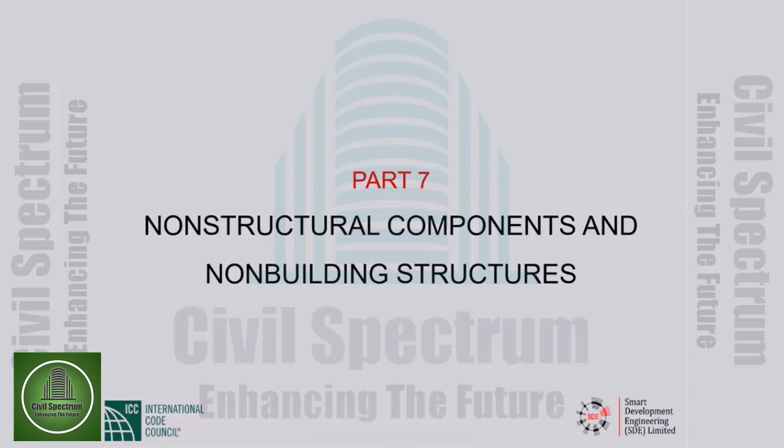ACI 318-05 allows the use of steel ordinary moment frame with some height and dead load limitations for structures assigned to seismic design category D and E. That is true. Does BNBC 2020 allow the use of ordinary moment frame for seismic design category D with similar limitations? I have not checked into that, but Dr. Rakib will teach a course on the steel chapter of BNBC.